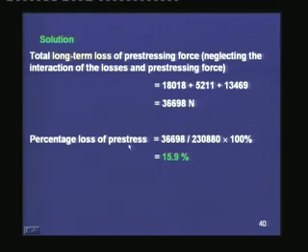The percentage loss of pre-stress is equal to this total drop divided by the pre-stress at transfer after short-term losses times 100%, and which comes around 16%.